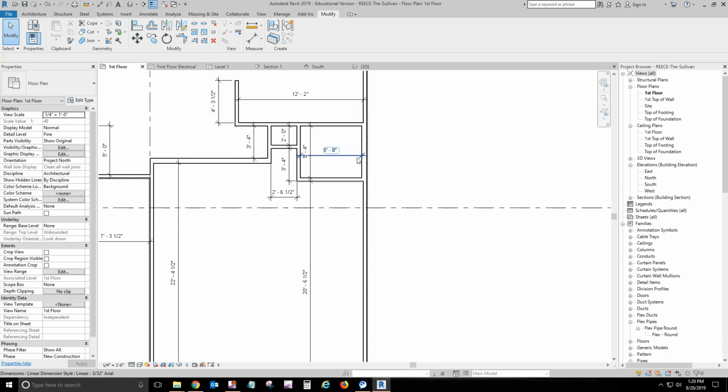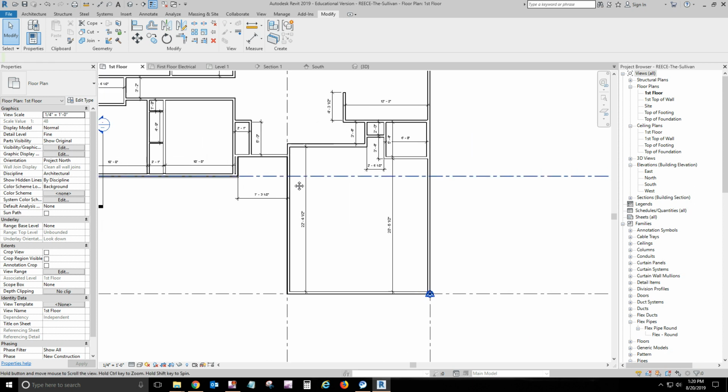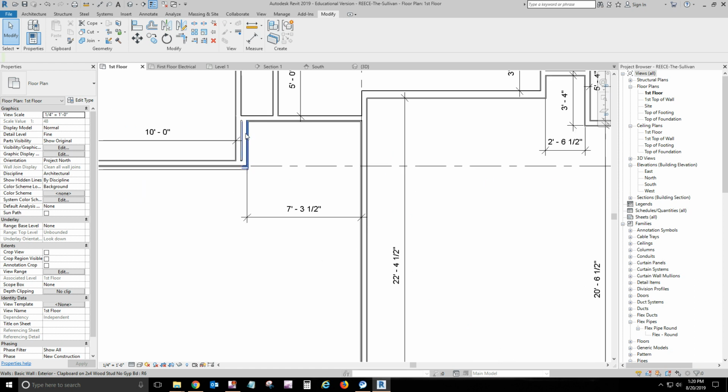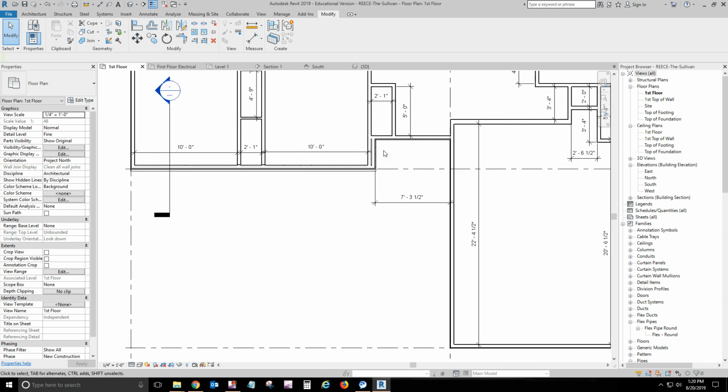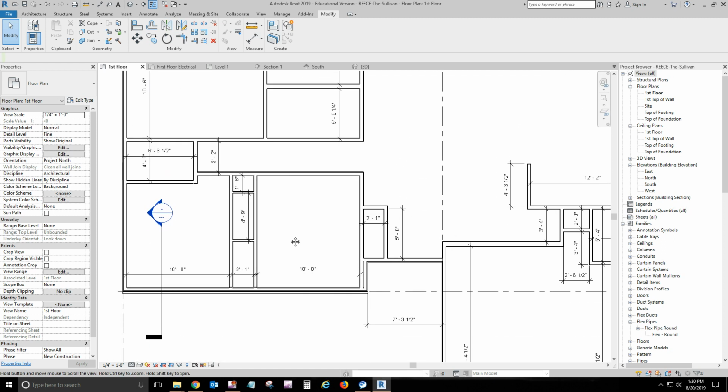You'll need an exterior 2x6 wall here for the laundry room with 2x6 studs. Right here, you're going to need a wall with no interior drywall for that area. And the rest of those are just the 2x4 walls. Now, while we're talking about that, also the interior walls, you'll have to create these 2x4 wood studs, 1/2-inch drywall, both sides.